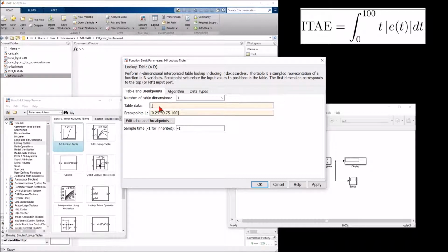And I will try to use some points in a way that this signal will simulate somehow the error signal, which is characteristic for the control systems. This means the error signal has usually positive and negative parts, but finally it becomes 0 if the control system works properly. So I will select these values 3, 1, -1, 0, 0.